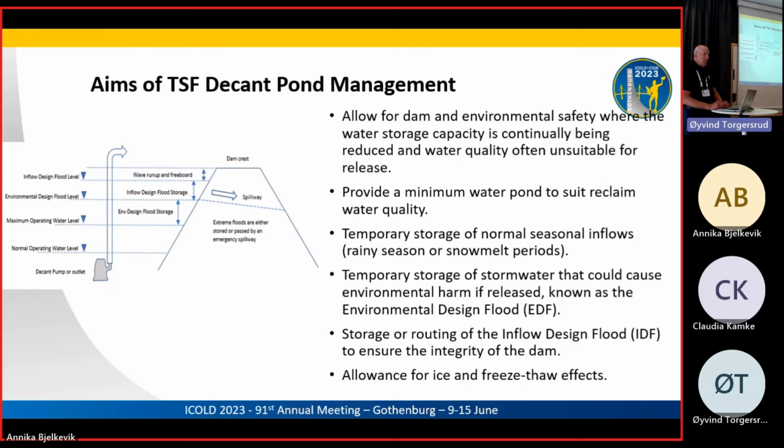And then we've got the environmental design flood, which is the temporary storage of any water that could cause environmental harm. And then above that, we would have either a spillway release or further storage of the inflow design flood.